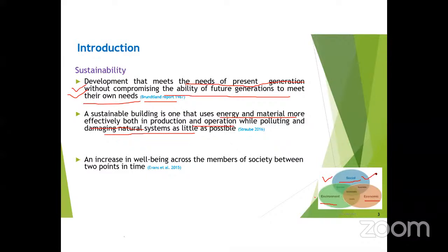Whenever I give the example of our COEP, if you come to the COEP and sit in the main building, it's a heritage structure, you feel the same climate in all the seasons. So that is a very good concept, the VADA concept, the best construction I can say. If you observe the VADA construction that is there right now also, the major interior portion is kept open to the sky. So the maximum amount of daylight is there, cross ventilation is there, and airflow is also good. So whenever we give the green rating, more rating goes to the VADA structure. It's not that you cannot construct using this conventional way.